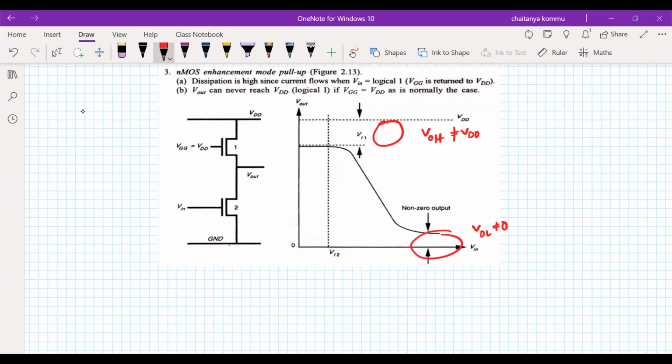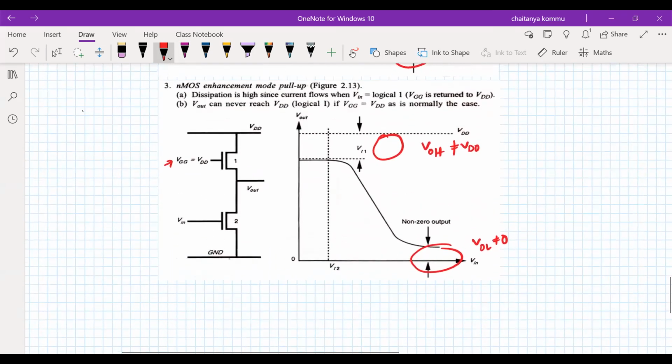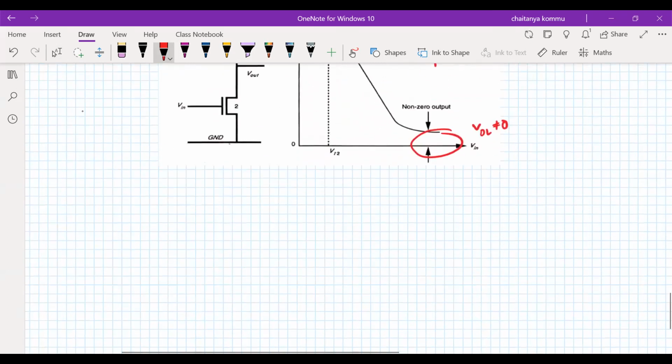One more thing is that we have to take the VDD normally from an external power supply, usually from another supply. So therefore, two supply voltages are necessary for this one. Okay, so of course, it also consumes power. The power is also high. Why? Because when Vn is equal to VDD, both the transistors are on. Therefore, power will be consumed for this one.